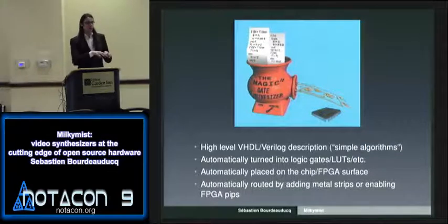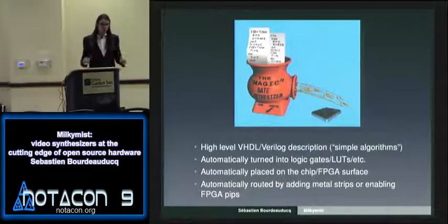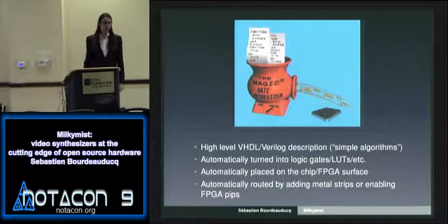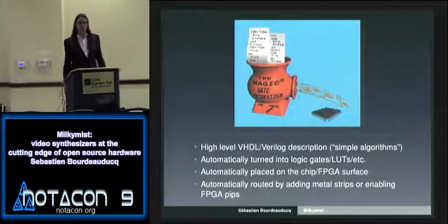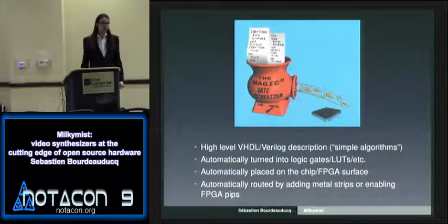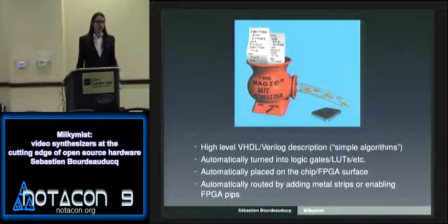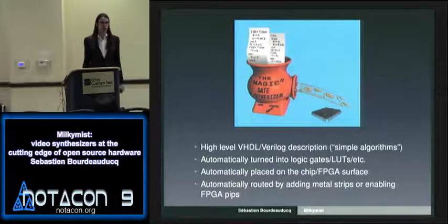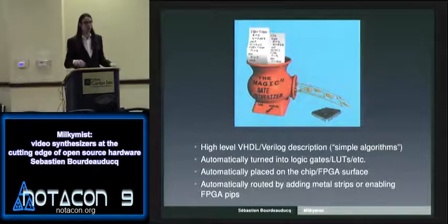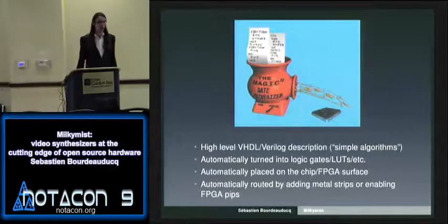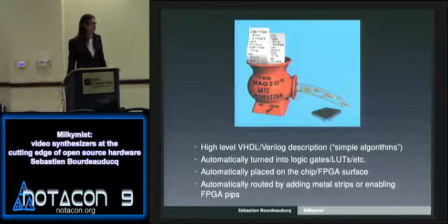When 2 standard cells or 2 lookup tables are communicating together, it's a good idea to place them close, so you don't have a lot of wiring and a lot of delays all over the chip. And the good thing is there are tools which do that more or less automatically. When you are using this synthesis flow, 99 or maybe 99.99% of the placement is done automatically using a software tool, which is actually not too complicated to develop.